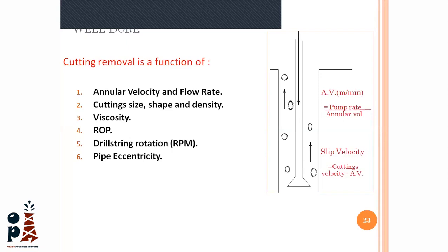He drilled two stands with an instantaneous ROP of 120 meters per hour. And guys, this is a very, very high number. This is a very high ROP. The result of this was that the flow line plugged, the whole well was plugged, and we could not continue. And if we tried to bump, the pump pressure was going up, and it was like a mess. It was a very unforgettable day.